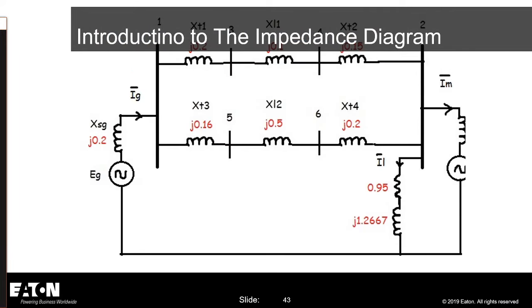Now, I'm a power systems engineer, and I've done a lot of short circuit and coordination studies. The first step of that is to create a single line diagram. Normally we take the single line diagram and put that into systems analysis software, SKM, EDSA, Easy Power, any of those types of systems, where we load the one-line diagram in and then perform studies off it.